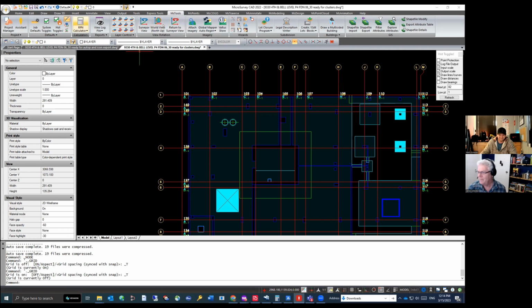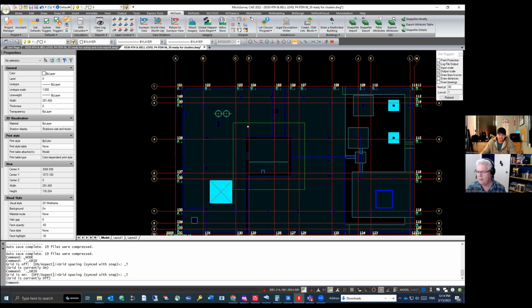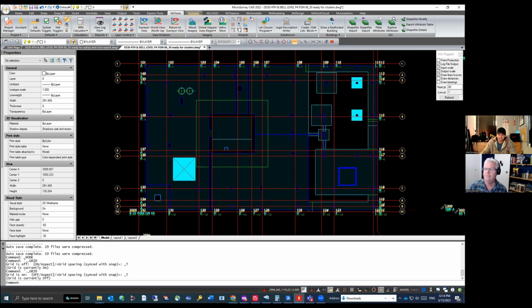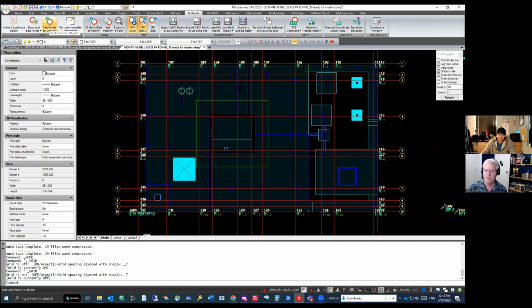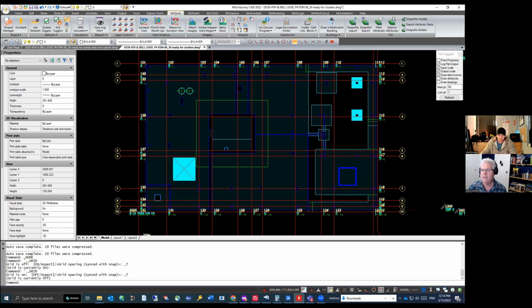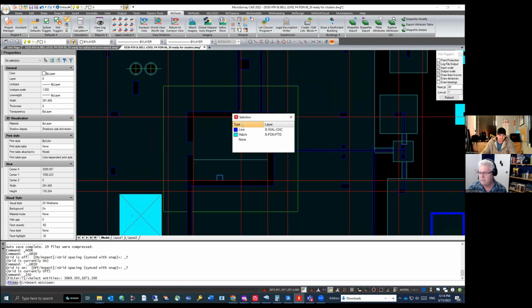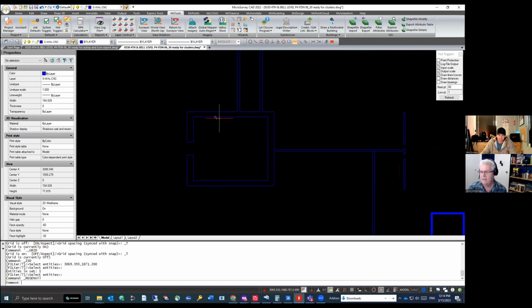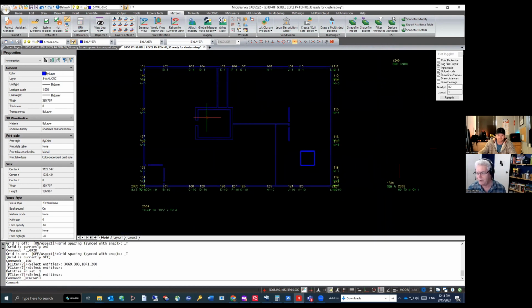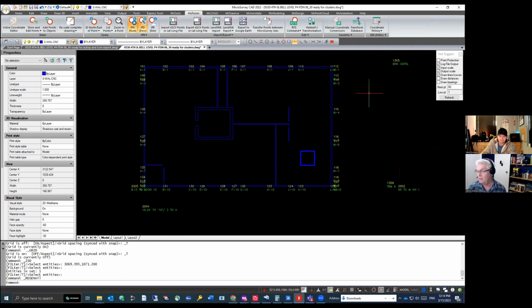Here it is. Okay. So I'm going to use the Add Points Objects tool and the Store and Edit Points tool. To do that, first of all, I'm going to isolate that blue layer, because that'll be some building footings. All that does is freeze all the other layers so that it's easy for us to work on. Then I'll show you those two point population tools.